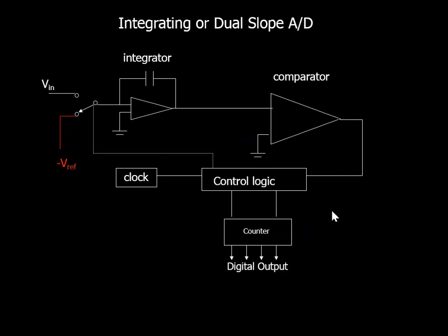This one here uses an integrator right there. This one's a little bit different in the fact that it doesn't have a direct counter that feeds to an A to D. What it has is a signal that goes up like this, and we know the slope of this signal right there. So we start this thing going up, and we measure the time before it trips.